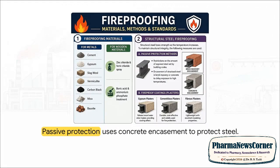Here's one of the biggest secrets of modern engineering. Structural I-beams, the massive steel skeletons of skyscrapers and industrial plants, actually lose their load-bearing strength incredibly quickly as temperatures rise in a fire. To stop a building from totally collapsing, engineers rely on passive protection methods like concrete or brick masonry encasement. By literally wrapping the steel in concrete, they dramatically delay the metal's exposure to those extreme high temperatures. And that buys people the time they need to evacuate.